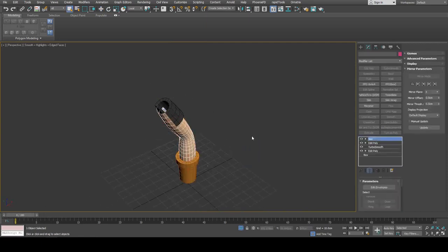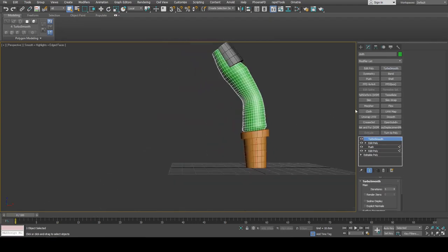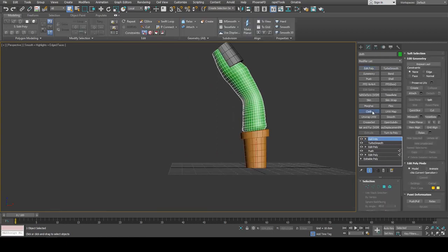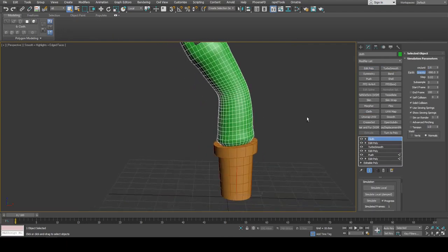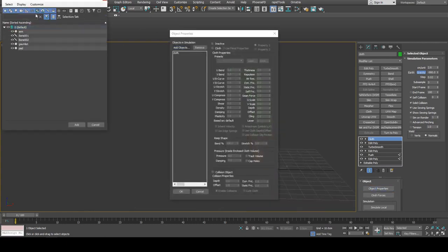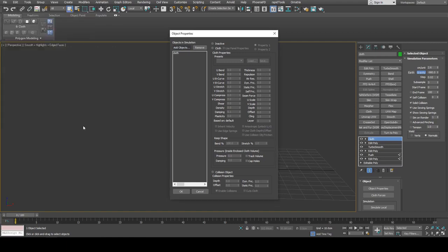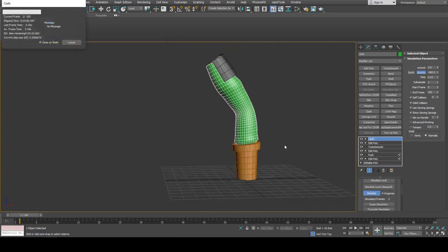All right, so now it's time for the cloth. So select this here. Maybe you can smooth things out a little bit. All right, so then I'm going to apply cloth. All right, so I'm going to go into the properties, add objects, and we're going to add the arm, the gauntlet, and the pad. All those three will be selected. Those will be collision objects. You can decrease the depth and offset. It's very close together, and we'll make the cloth cotton again. All right, so let's see what this gives us.